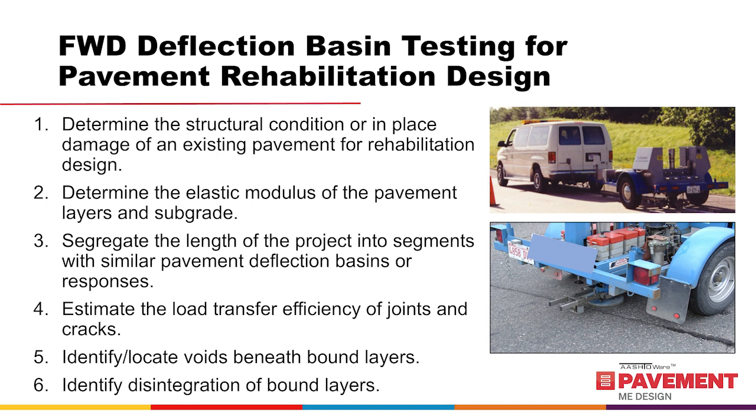soil strata. The fourth area is to estimate the load transfer efficiency of transverse joints and/or cracks in the existing pavement. Load transfer efficiency has an important impact on the occurrence of cracks in the asphalt overlays and long-term condition of the joints in a jointed concrete overlay through its rehabilitation life.